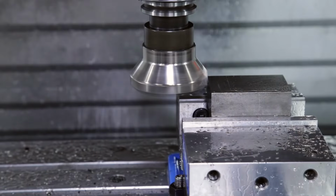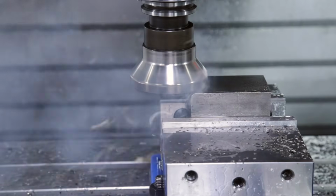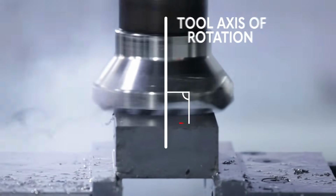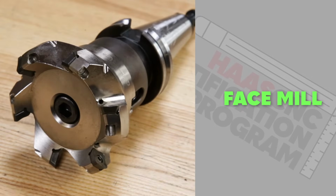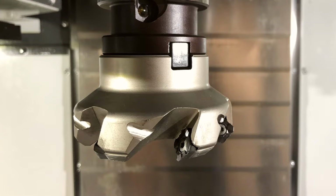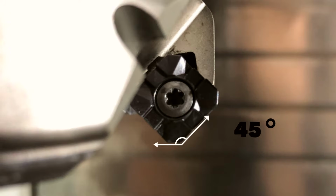Now here's a different type of milling cutter where the surface to be cut is perpendicular to the tool's axis of rotation. This is called a face mill because its primary function is to cut the face of a part. They come in different configurations, but the most common is a 45-degree angle on the outside.